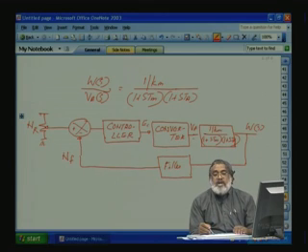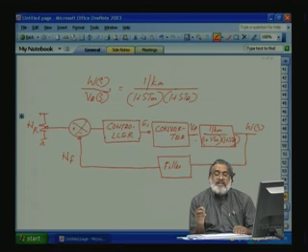Applied voltage also has to be dependent on the present current available to the motor. We should always see to it that VA is applied in such a way that the machine, during acceleration and deceleration, while giving positive torque and negative torque, should not be drawing more than the maximum current. So an inner current loop is required.